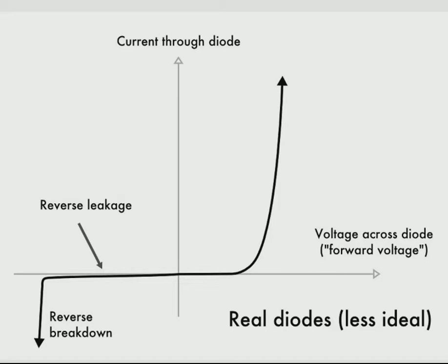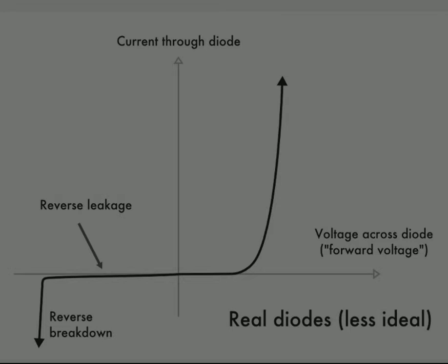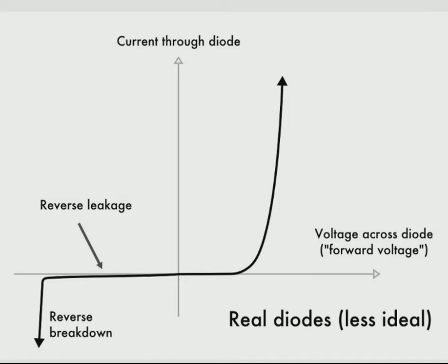Hi, so here you can relate the IV curve of a Zener diode to that of a simple diode. As explained in the previous module, we've seen that the Zener diode works primarily in the reverse bias region. So how is that? You can see this is the forward characteristics of a normal diode, and it is also the forward characteristics of a Zener diode. This is your current I, this is your voltage across the diode.